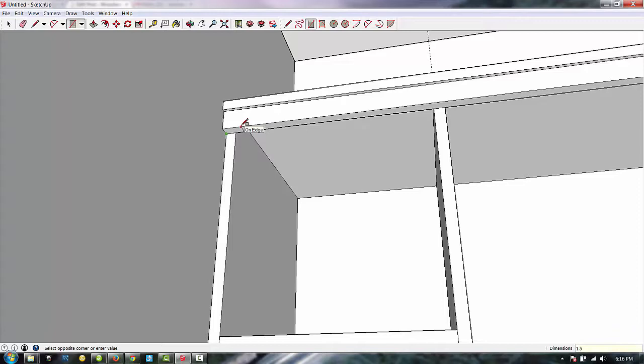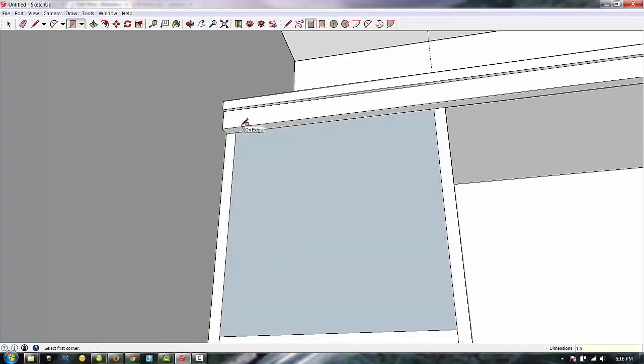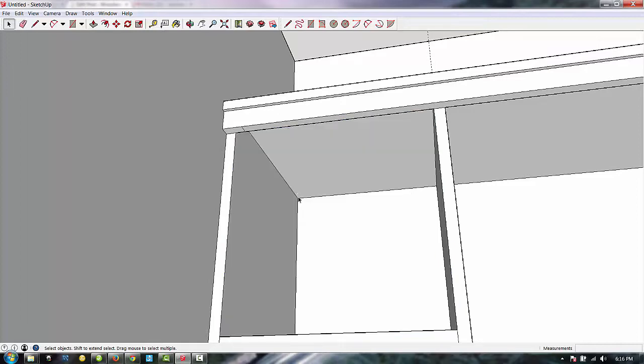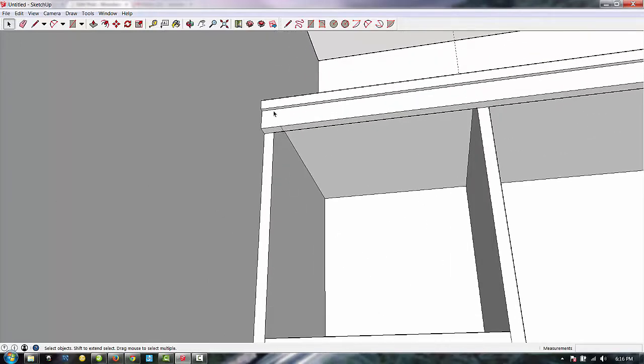So I will just do 1.5, and don't worry about that closing up. It's an easy fix to get rid of that. Just click it once with the cursor and hit the delete button, and it deletes that. It's just SketchUp is sometimes too smart for its own good. You can close spaces just by simply drawing a line along a side.